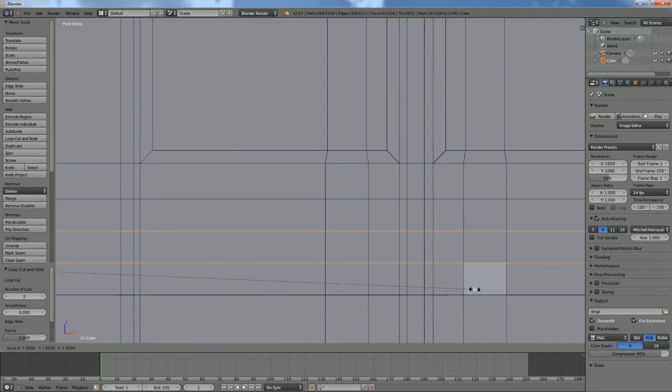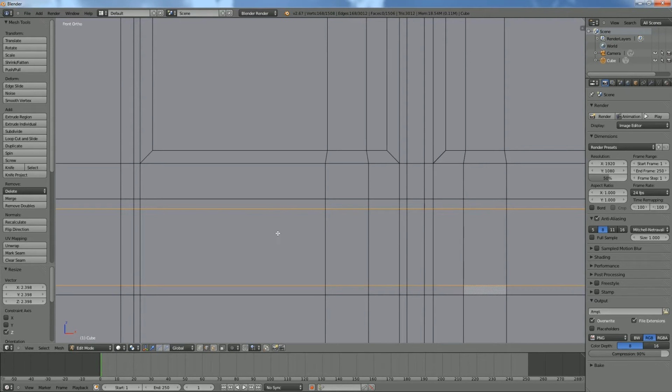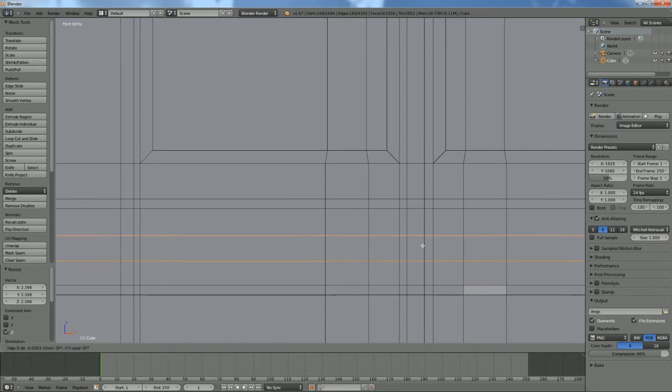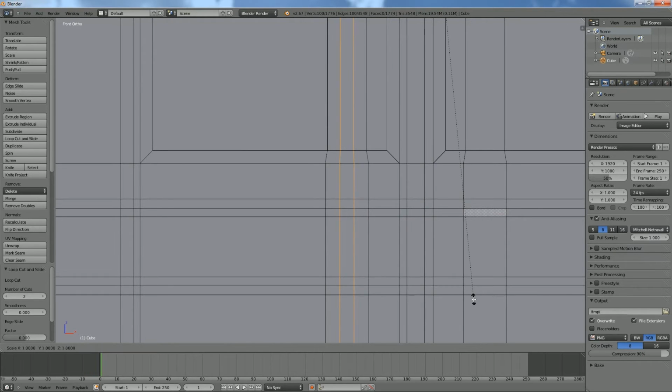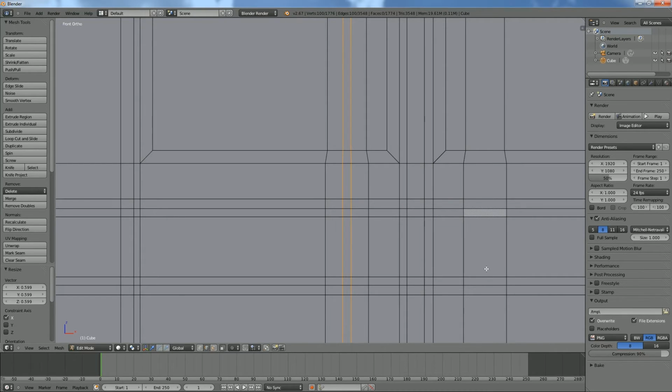and right click, and I'm just going to scale on the Z to about the height that I want to see for the outside of them. So out there, and do the same thing. Scale by pressing S and then Z, and about that thick. So looking about at these faces here for our handle are going to come off. We'll make it a little thinner, so we'll go Control R on the vertical part, and we'll scale that in on the X, and same thing over here.